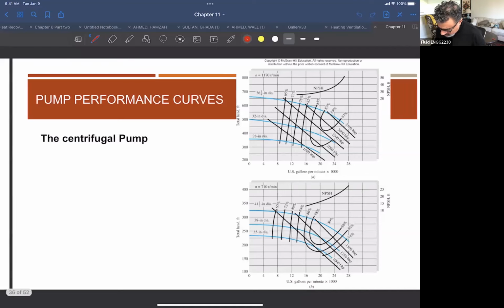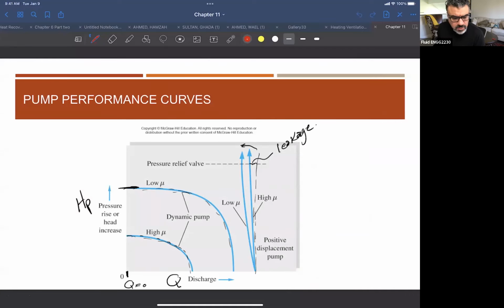Okay, so last time we talked about the centrifugal pump, if you remember, and we covered a very important difference between the positive displacement pump and the hydrodynamic pump. We actually focused more on the centrifugal pump for this reason. And if you remember, we presented 2 types of performance curve for this pump. For the positive displacement pump, the pump has to operate in order for the fluid to move outside on the delivery side, like pushing the fluid out.